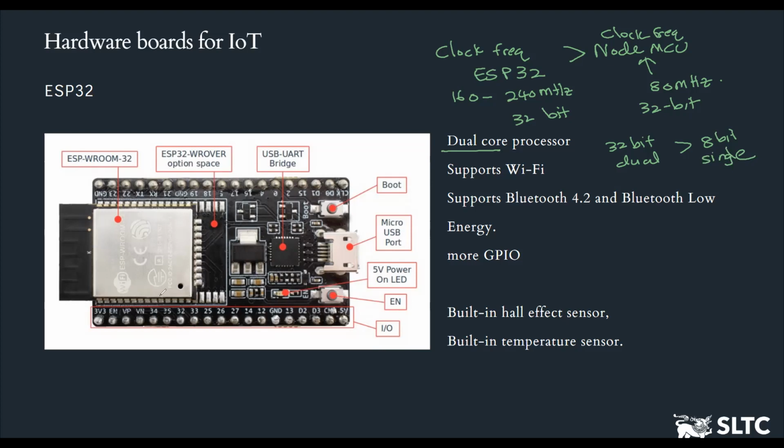And as we discussed multiple times before, ESP32 supports Wi-Fi, Bluetooth, and Bluetooth low energy communication technologies, and those technologies are inbuilt in the system itself. Sometimes these technologies might not work sufficiently, and at that time we may need to connect a separate external antenna or Wi-Fi antenna to get the Wi-Fi signal properly into the ESP32 microcontroller board.